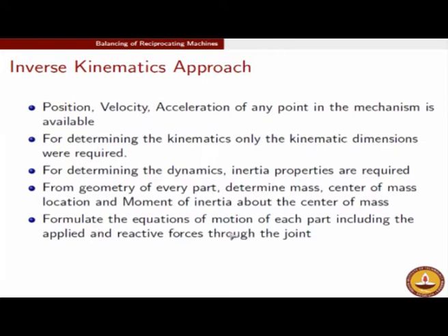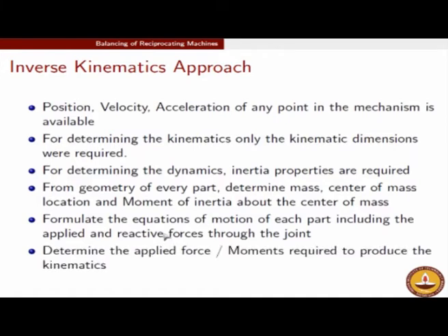And today, to start with, what we are going to do is formulate the equations of motion for each part, and the main challenge in that is that we are going to account for not only the applied forces but also the reaction forces which come from the joints. That will be clear to you in a moment. As a result of this analysis we will be able to determine the applied force which ensures the desired kinematics. Remember, the kinematics that we want is that of uniform angular motion of the crank. To get this uniform angular motion of the crank we require to apply certain kinds of forces. So, through this analysis we will be able to determine what forces or moments will produce this kind of motion.